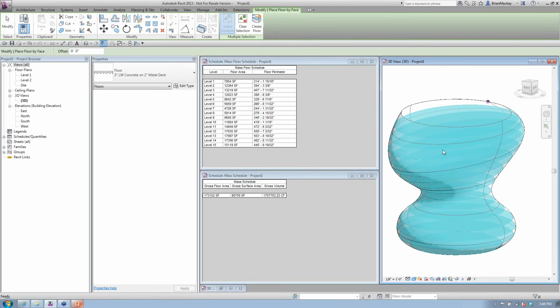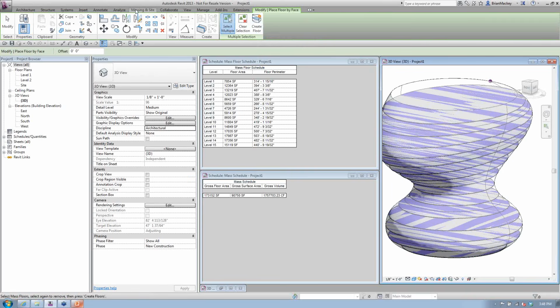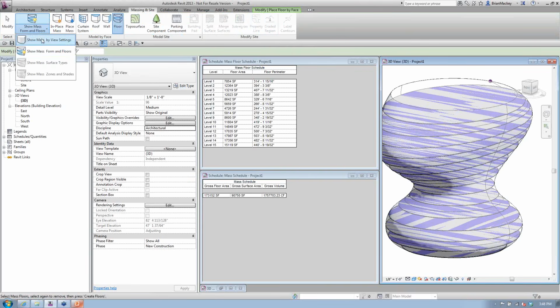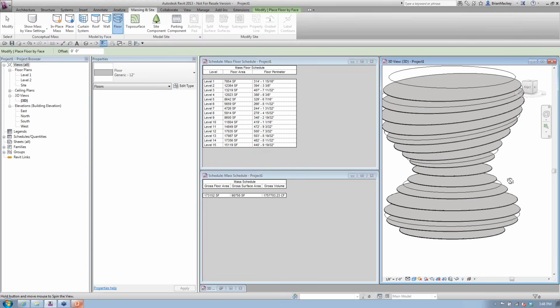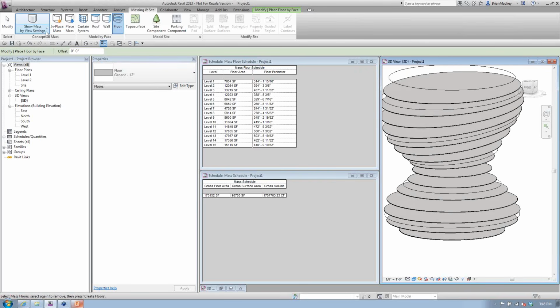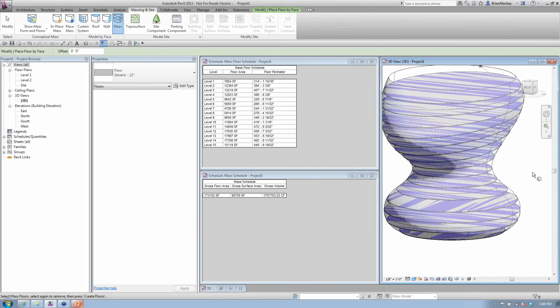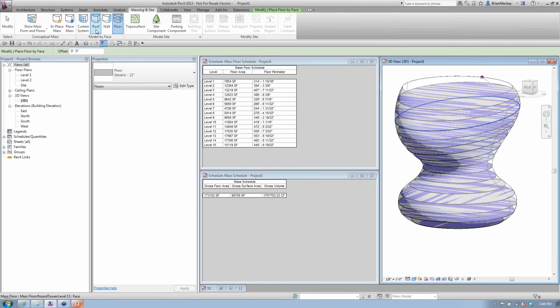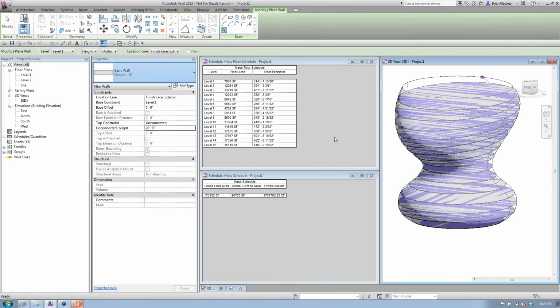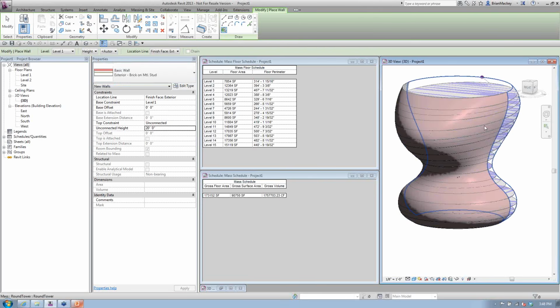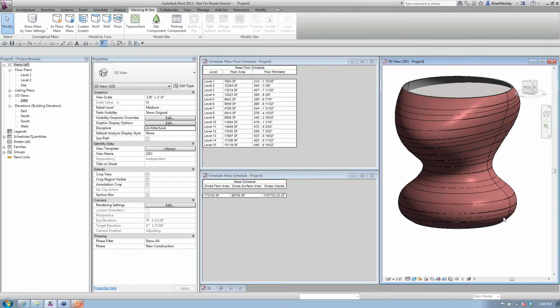So we'll create that floor, and now Revit has put floors inside of there. If I go back to my massing and turn the masses off again, you're going to see I just have floors sitting inside of this. All right, so we'll turn the masses back on. Once those floors are done, let's put a brick wall by the face. We'll do wall by face, brick on metal stud. We'll create that side, we'll create that side, and boom. Turn the massing off so you can see, ooh, look at the pretty brick.